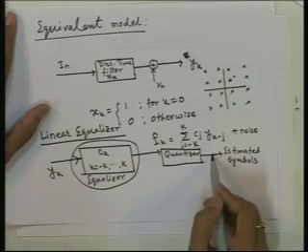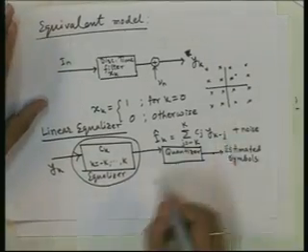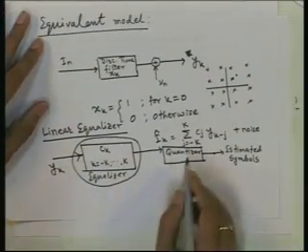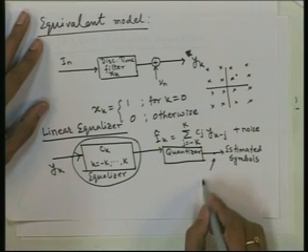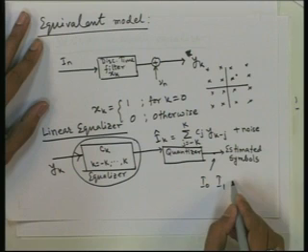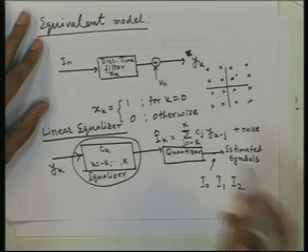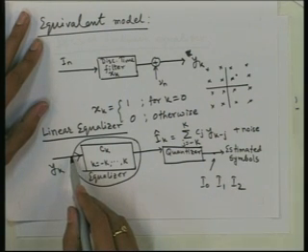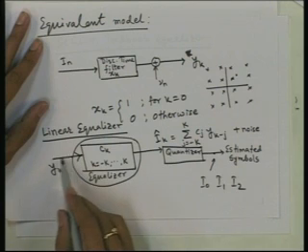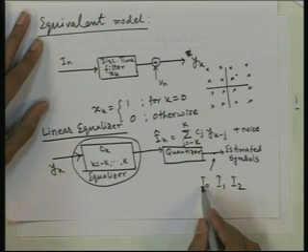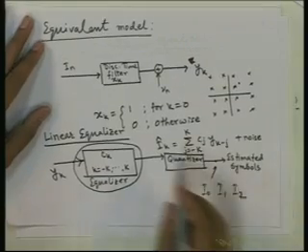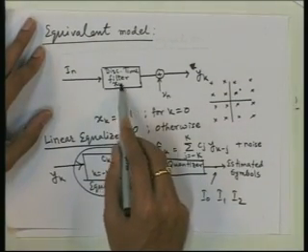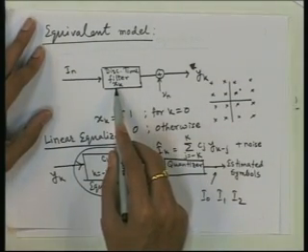So, in other words, when we have received here, we have already decided the values for I naught, I 1, I 2, and suppose we are receiving the future symbols here. The interference caused by I naught, I 1, I 2 is known to us, because we probably have estimated this x k, this filter.